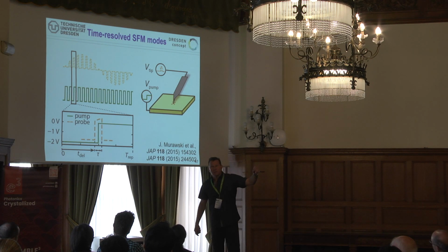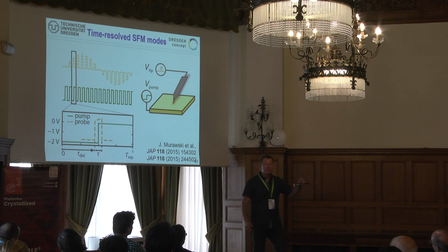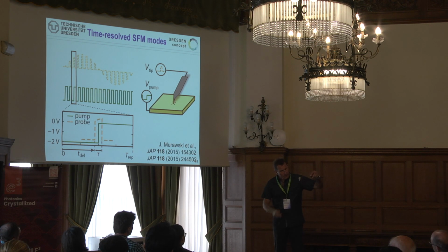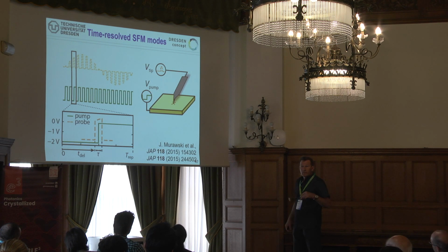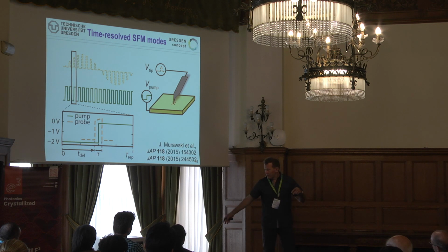So that means what I can do is actually kind of an electrical pump probe, which means I'm getting my charges in from the right, I'm standing here, and I'm going to make a coincidence experiment saying, hey, charges, are you already here when I'm doing my pulse on my tip? If they are there, fine, I get a 1. If they're already gone, or if I'm too early, delay line, then I get a 0 signal out.